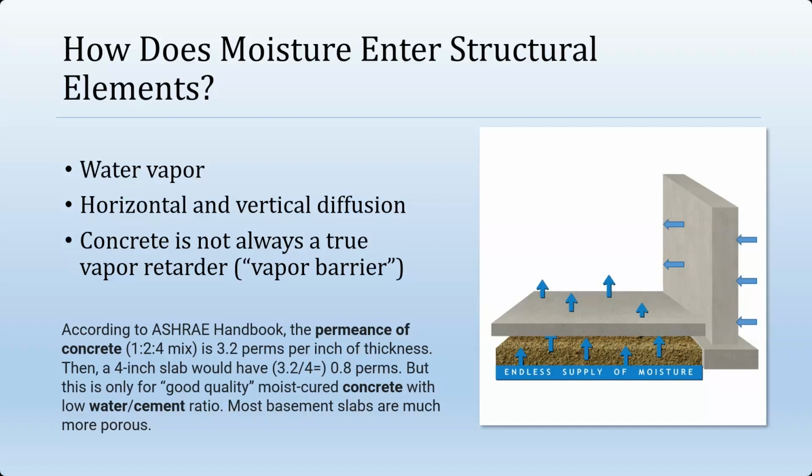Inevitably, we're going to create a usable, viable space below grade, and of course, that's going to be conditioned. So if we're dehumidifying much of the year because we're constantly battling the available moisture underneath the slab, if we're going to condition it to say 30%, 35% RH, and we have 100% RH on all 5 sides, the vertical foundation and underslab conditions, we're going to have vapor drive.